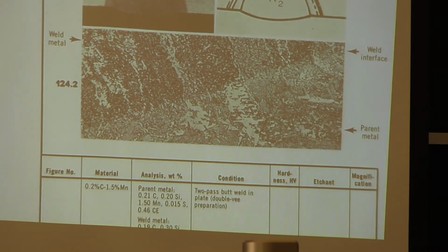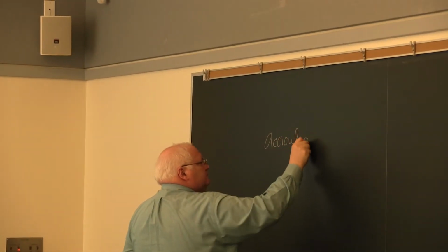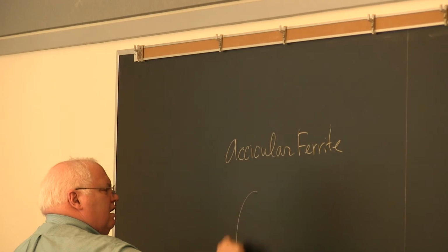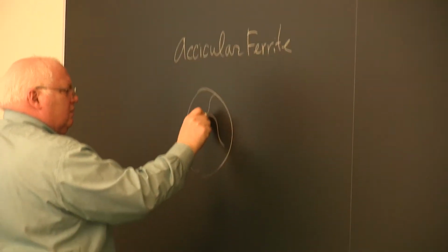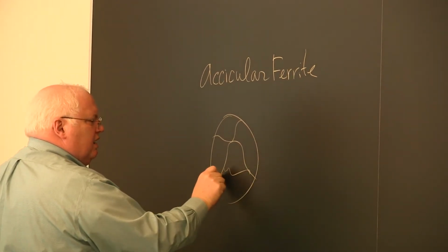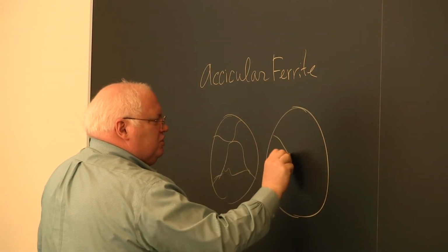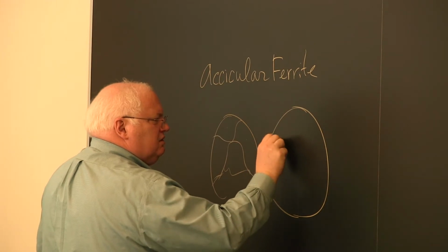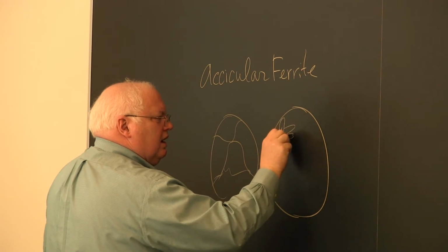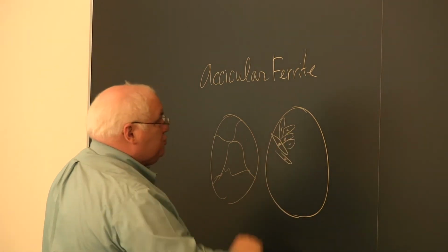I'll write it over here. So a regular steel grain cooling down, if you look at it in a microscope, will look like a bunch of grains of different sizes. They should be 120-degree angles at the intercepts and stuff. But you have grains like that. But the weld metal will be a bunch of needles, and at the center of each one of these needles, if you look at it in a transmission electron microscope, will be an oxide inclusion. Okay, I can't draw them all, but it's a fine grained structure with needles.